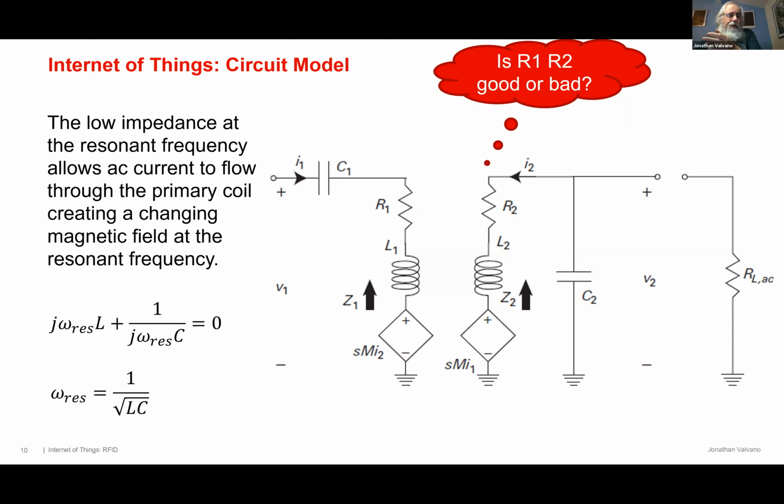And so we're going to pick the C's so that whatever frequency we're oscillating at, this thing is in its resonance, which means it couples very quickly. And we got two C's. We got C1 on the reader, on the generator, and we got C2 on the receiver, on the tag. Okay, so we have that free variable, which will basically remove the consequence of the R because they subtract each other. I probably missed a negative sign in my other equation.